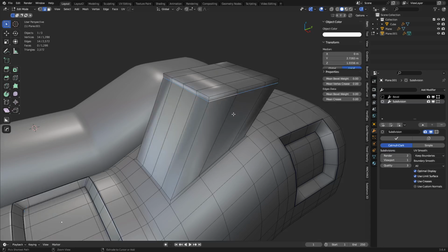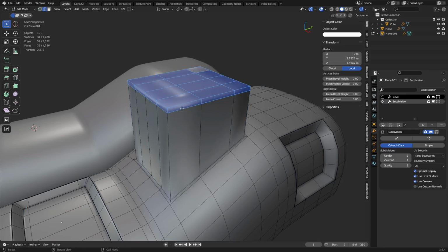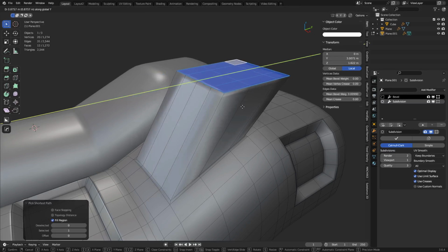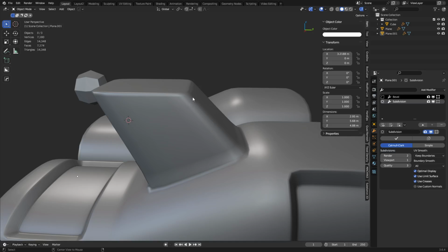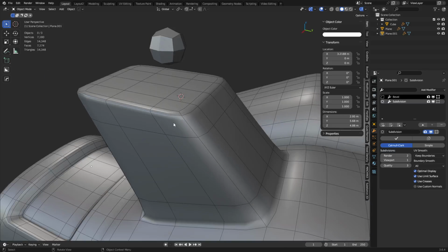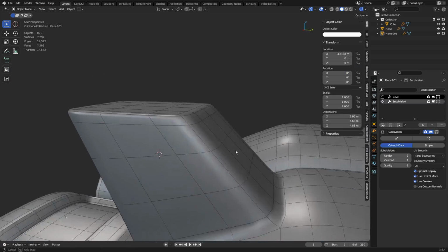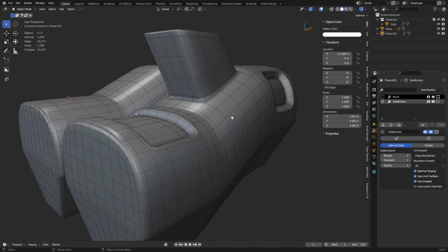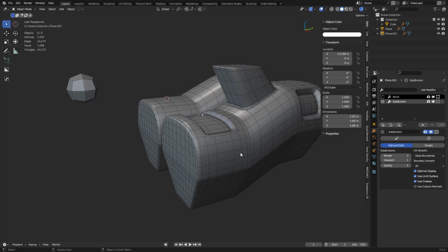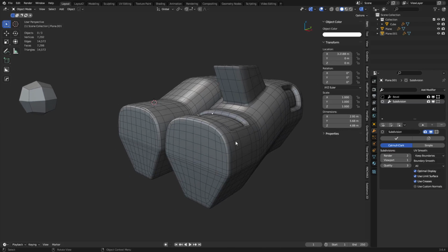And when you're doing those bevel weights, it's not quite the same. What ends up happening is you do like a boundary select, you do your bevel weight. All this geometry up here, you can move it, no problems, and that recalculates that little angle there. Perhaps you add some in the middle though, maybe it wouldn't go so easily, but I think you get the idea. So you can make some pretty interesting shapes rather quickly, and have a little bit of fun with it. You're still going to do all your regular subdivision tricks. There's no cheating way of doing subdivision that I know of, anyways.